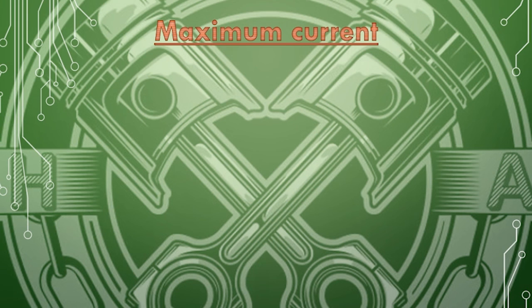So we are going to be calculating the maximum current now. So again, we're going to be doing I, then square root again, and then power over resistance. So that is the method that we are going to be using now. So we're going to be taking the square root in the calculator again, 100 divided by 8. That's going to give you the maximum current coming out of those speakers when they are in full operation of 3.5 amps.